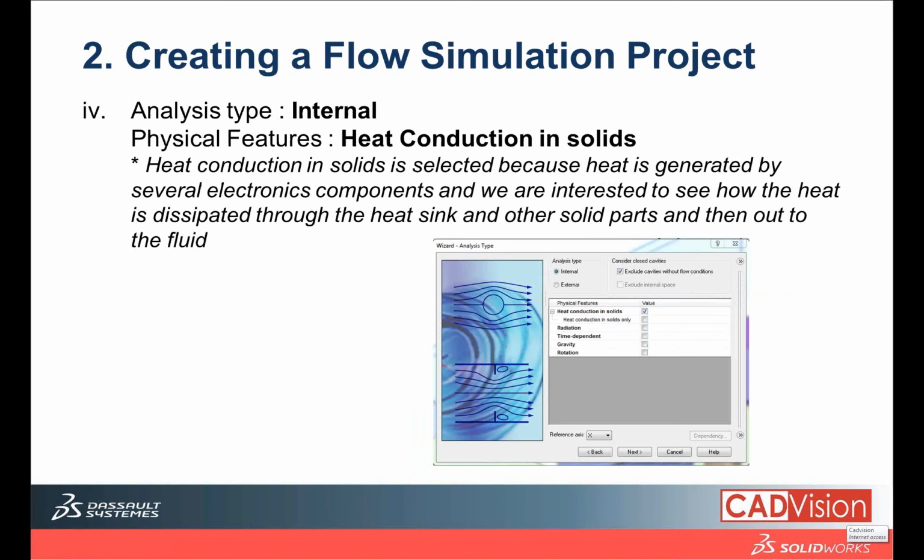Still in creating the flow simulation project, in the wizard we can select whether it is an internal analysis or an external analysis. Then check heat conduction in solids, because we would like to consider also the heat dissipated from the solid itself, or the heat transfer between solid components. Each of the components generates heat here, and the heat will be dissipated to the surroundings and also between solids.